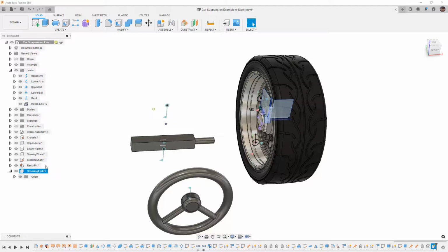So before we do anything, I'm actually going to move that coordinate system. And the main reason that you might want to do this is if you're using this conceptual model to then eventually design all of your components, then you want to make sure that those coordinate systems are in a reasonable place to start your design. So if you're using solid bodies to rough in the geometry and eventually translate that to something else, then we want to make sure that we do move it.